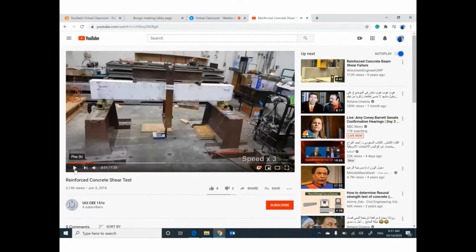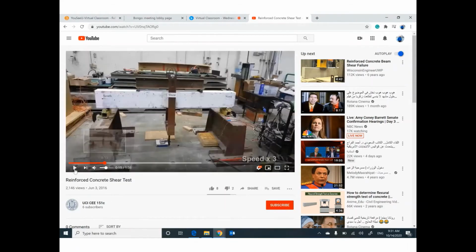Guys, we have a beam. This beam is supported here by this roller support. Can you watch it from the left or from the south direction? Anyway, we have another support on the other side. And we have a concentrated load at this location coming down and at this location coming down. So just to remind you, this load will apply a force coming down, and this support will apply a reaction coming up.